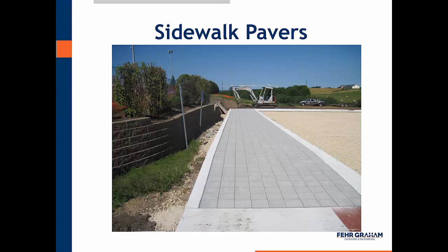What we're seeing here is a paver that is a little more uniform in texture and surfacing, a little better for pedestrians versus vehicles. A little tighter joint, but works well. It's a smooth surface. Really works good for pedestrians. And then you can see off to the right, we have that stone base. We're getting ready to be able to put the pavers down there.